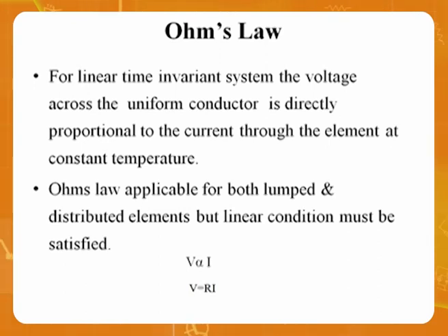It's not changing with the amount of current. It's not changing with temperature. These three words you need to be very clear about. Everybody only talks about temperature, but you must understand that by temperature it is fixed. So R has to be fixed, including a uniform conductor. I said uniform conductor because it should be uniform at every point. Otherwise, some distributions will develop and Ohm's law may also fail. So the conductor should be uniform and linear, it should be time invariant, and finally, temperature is constant.